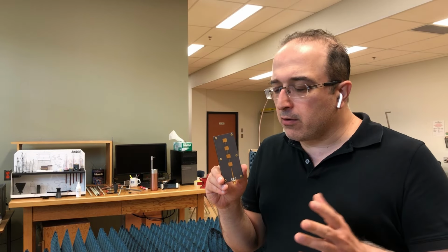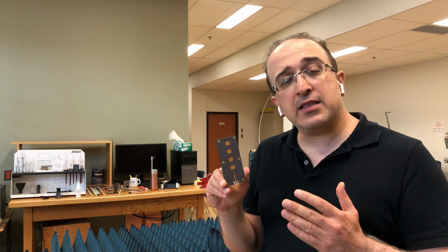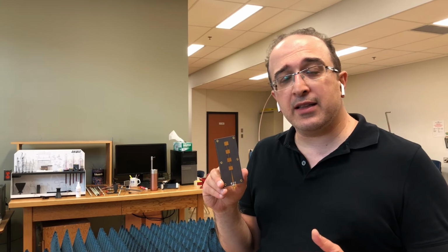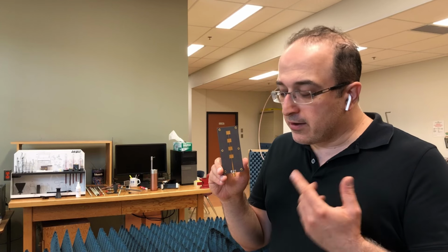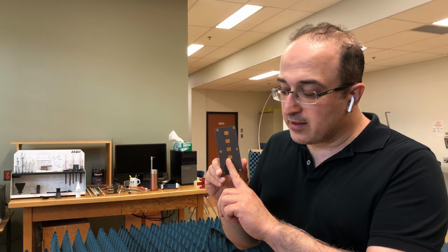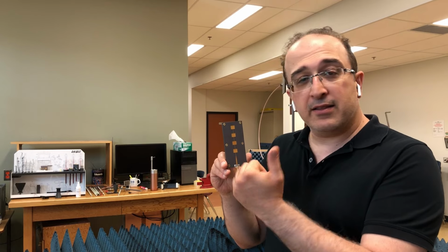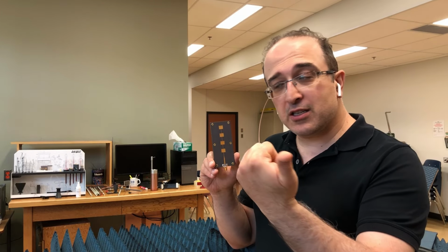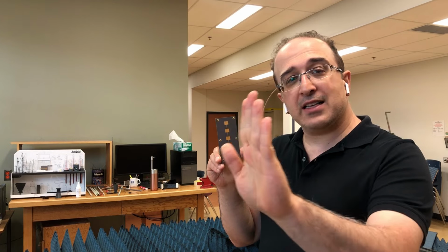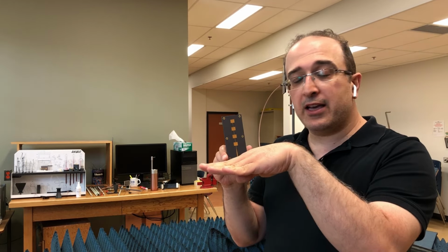So now we're gonna focus on the E plane and H plane data acquisition. Similar to parallel fed, let me remind you that the fringing field over the patch is in this direction right now. The direction of maximum radiation is toward you. So in fact, this is my E plane, and this would be my H plane.